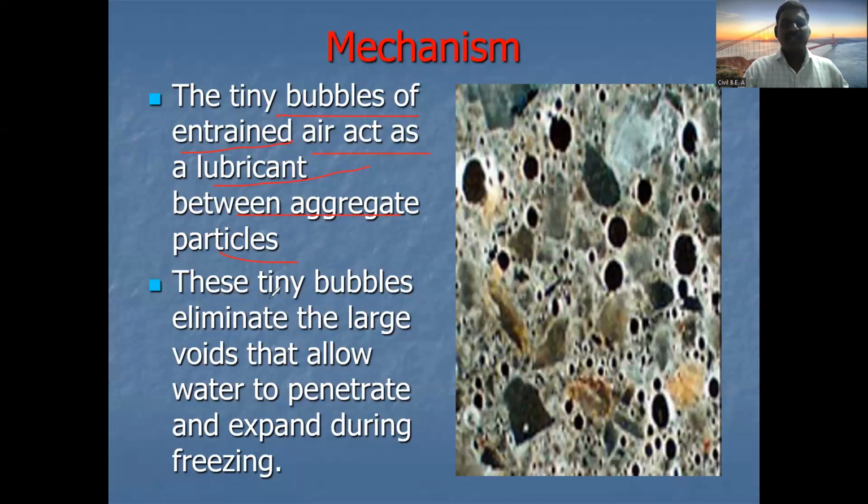So these tiny bubbles eliminate the large voids and allow water to penetrate and expand during freezing. So the bubbles are eliminating whatever large voids are there, and allowing the water to penetrate and expand during the freezing process. In this way the mechanism is developed if we add the air entraining agent into the concrete.